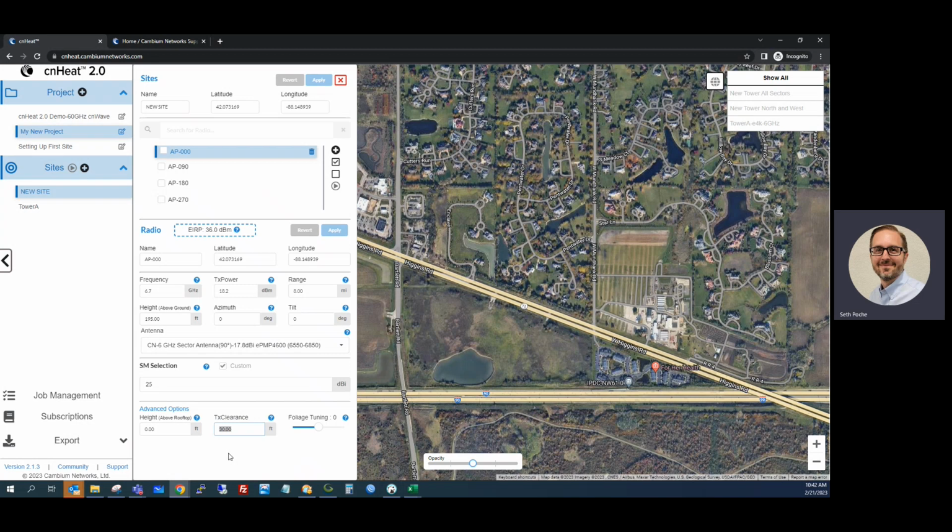And so you set your transmitter on the guy tower, it would be off just by a little bit, just by nature of it's very difficult to get exact, accurate, within-meter placement. And so you would end up almost with a peace sign type of shadow emanating from the tower. And then those shadows get larger and larger as you get farther from the tower. So the obstructions being very close would cause problems and have these half-mile wide shadows as you get to the edge of coverage at 8 miles or 12 miles.